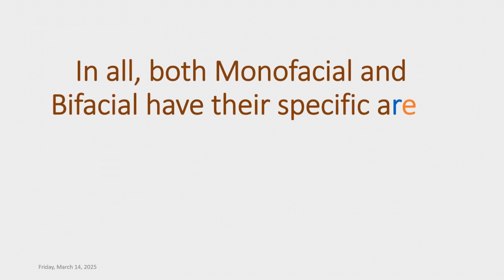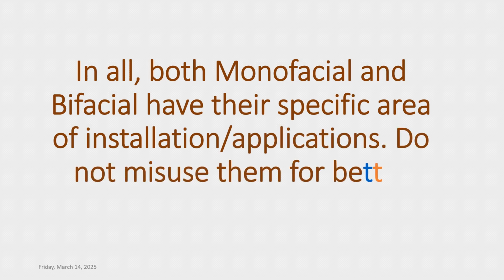In all, both monofacial and bifacial have their specific areas of installation or application, just as I've explained. But the most important thing to note is that bifacial are not good for rooftops, while monofacial you can use for both rooftop and ground mounting systems. So do not misuse them, for better efficiency.